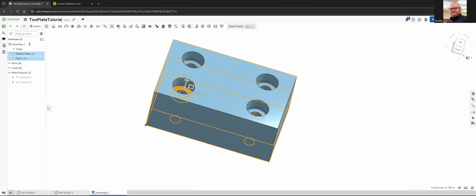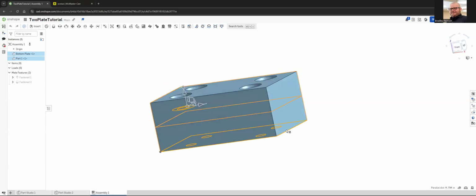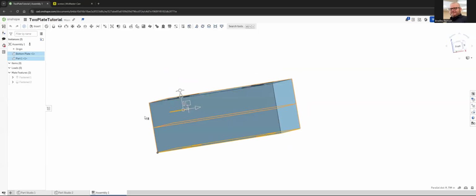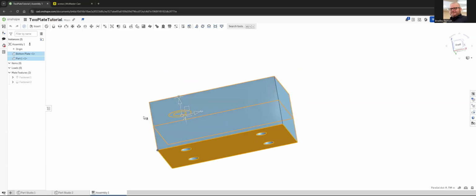Oh, as I'm looking around, I do see measure details down in my bottom right hand corner. That is cool. So sort of like how Microsoft Excel does it, where if you select cells, it automatically gives you the total. Here I've got a parallel distance of 0.75, which is exactly what I wanted to know, right? So I need a 3/4 inch long screw, probably just a little shorter, just to guarantee that we don't pop through the back.